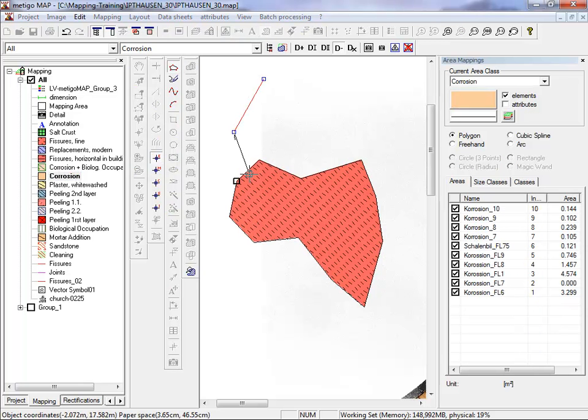If your cursor meets an existing line, you can see how the left or right endpoint of the line is proposed to you. With left mouse click, it will snap to the endpoint and you can go on to the next point and another and another.